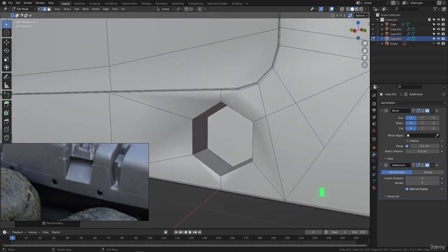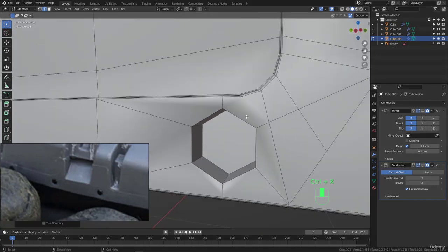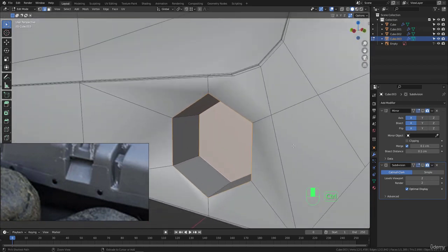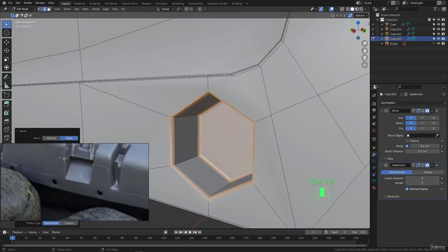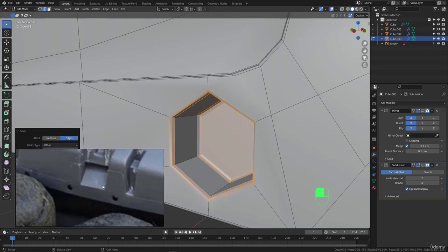After we add the bevel, we can bring this back, because as you can see, this edge, we have this line and this line. This line goes in this direction, and here we get a sharp angle. That may affect the bevel when we add a bevel here. So I prefer to delete it temporarily and keep this one, and after I finish the bevel I will connect it. So hit Ctrl X, go to edge, alt click, alt shift click, grab those together if you like, hit Ctrl B, and let's add 0.6, and that will be enough.